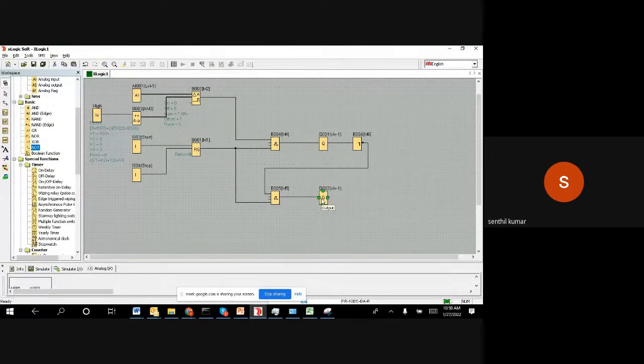Right, Q002. Now the requirement is that this valve has to open after the first valve closes and the system is running. Also, if the tank 2 level goes less than 500, we want to stop it again, right? That logic also should come. So I will copy the top one. This is similar logic for the bottom also.